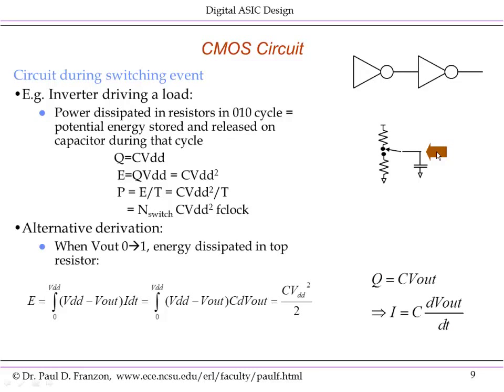Now, when the node switches, power is dissipated in these nonlinear resistors. Right? Just like power is dissipated in a heating element when you run current through it. And that is the loss mechanism. That's where the power ends up as heat being dissipated in these nonlinear resistors that I'm using to approximate the NFET and PFET.